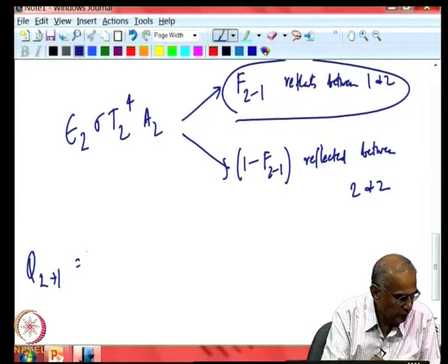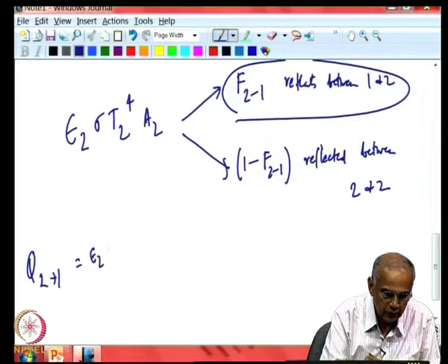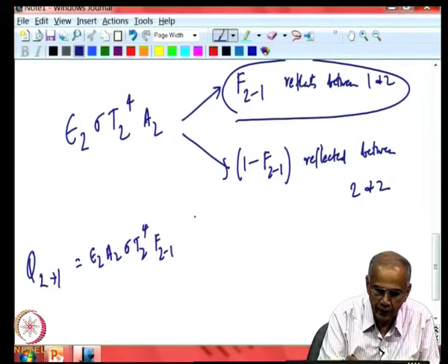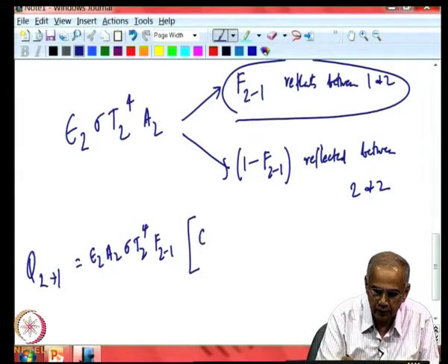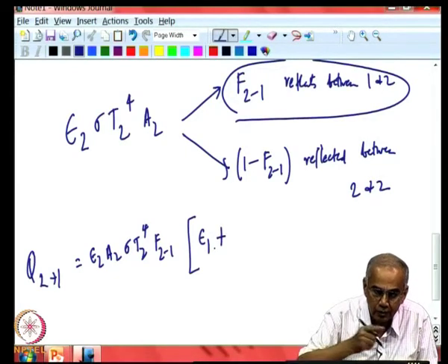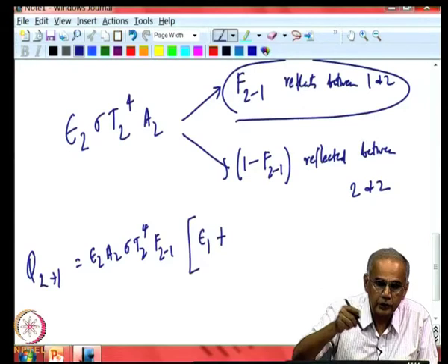from 2 to 1 as the first ray which is emitted by 2, hits 1, and is absorbed by 1, assuming a gray surface here, so alpha equals epsilon. Then if it is not absorbed, it will continue to be reflected between the two surfaces.